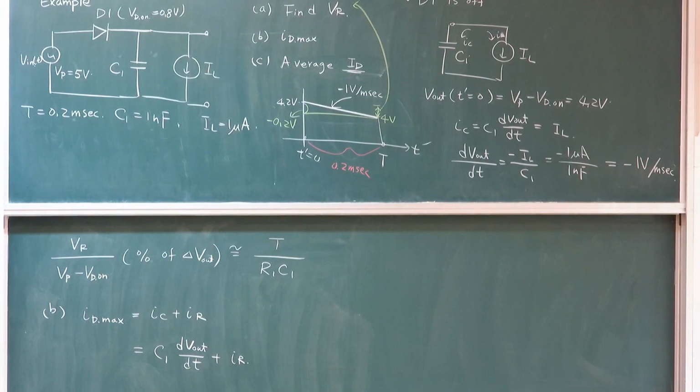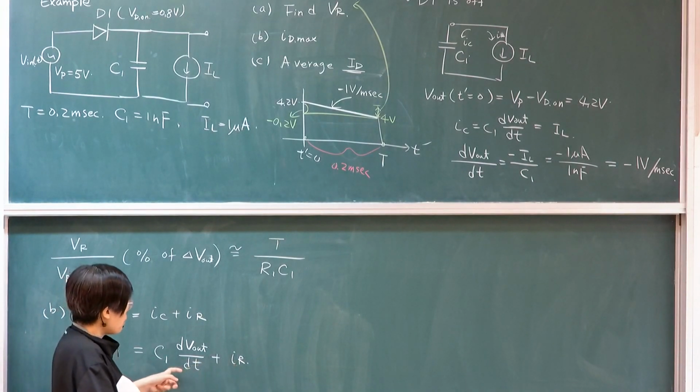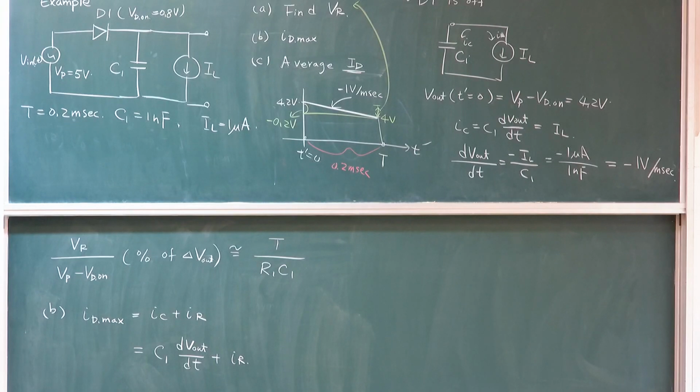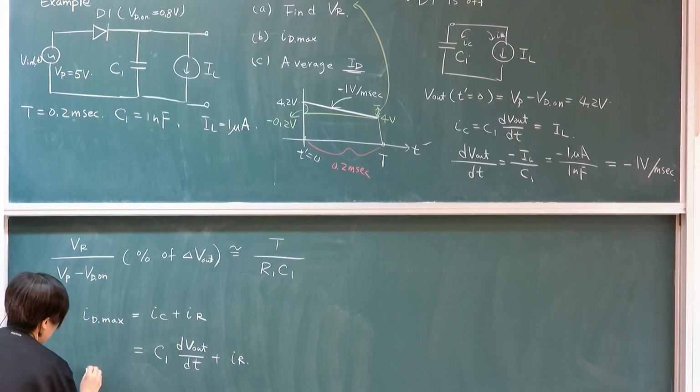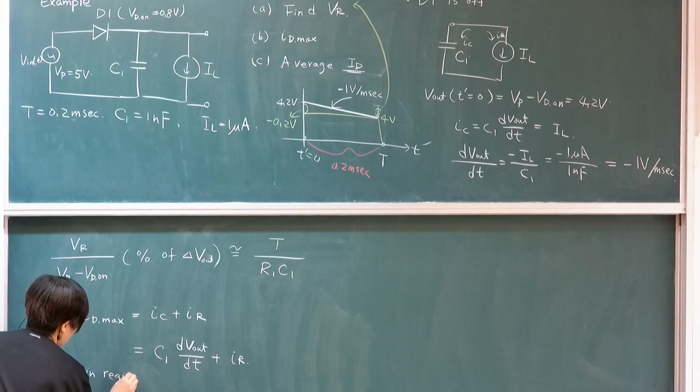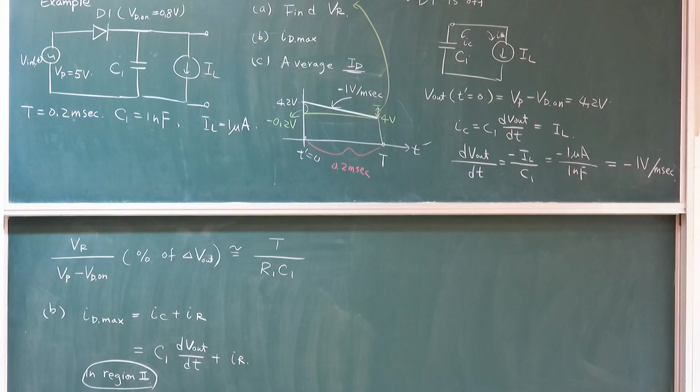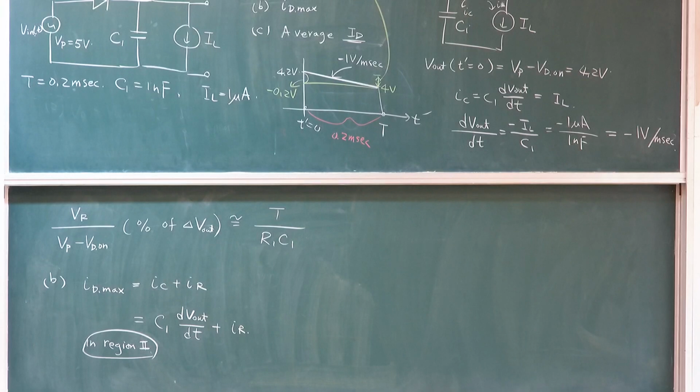This is a little tricky because your output voltage, your supply voltage, depends on the end, but this will depend on the beginning of the charging period. But anyway, in the chart, this is in this phase. We'll not consider the first charging period, we'll only consider this one. So you're assuming that it's in region 2, with diodes turned on. So you're assuming that it actually happens at this particular point, because at this point, you actually have the fastest ramp rate that will lead to high current.